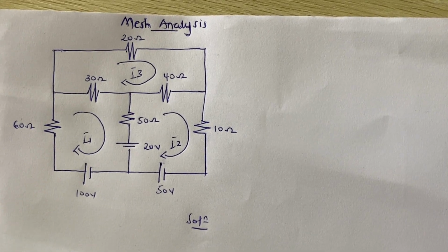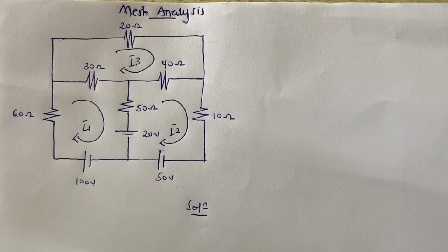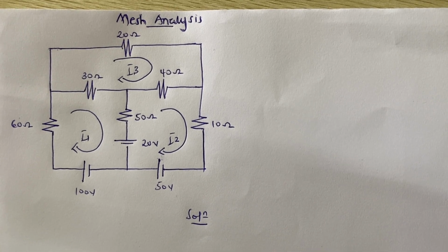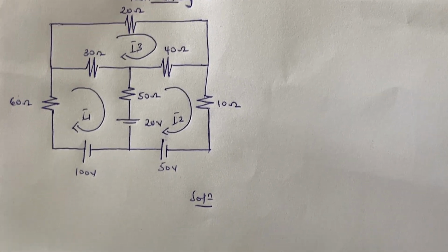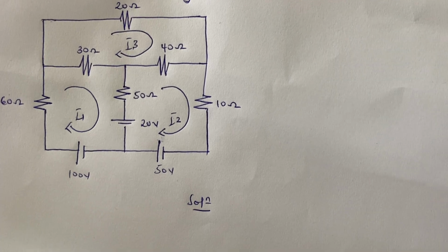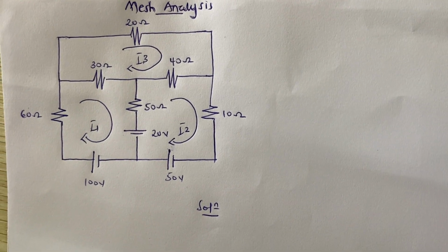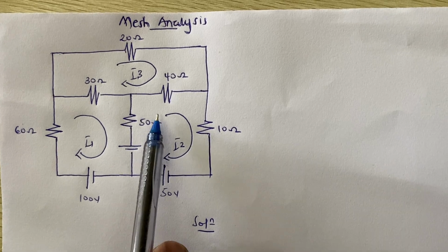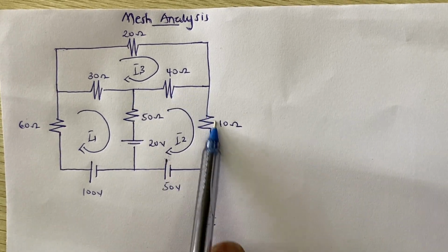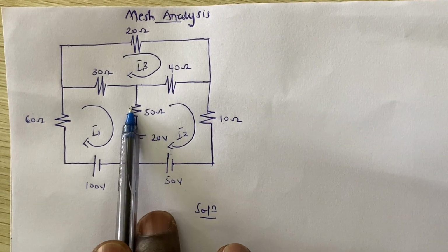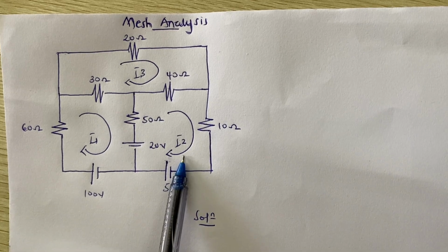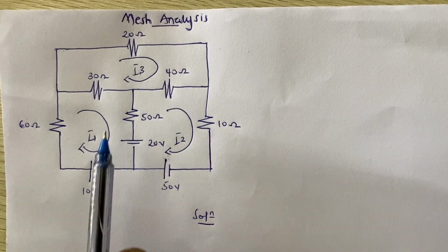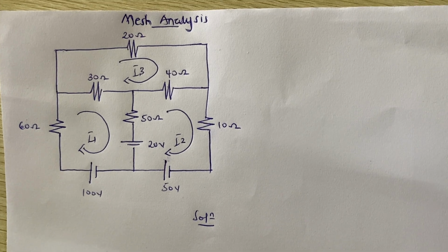But then the question is, why is it that we are assigning current to it, but we are interested in the voltages instead? The reason for that is because from KVL, our Kirchhoff's voltage law, we know that the algebraic sum of voltages in a closed loop sums up to 0, right? So it means that we are assigning current, the same amount of current is going to flow through it, but the algebraic sum of these voltages should give us 0. So with the help of our current, now we can find the voltage drops across each resistor, right? So now let's kickstart.